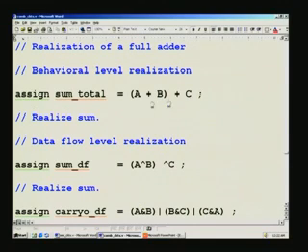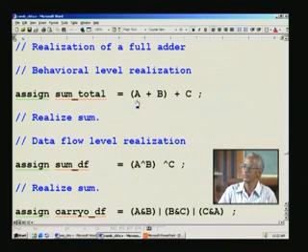We have seen 3 types of full adders. One is a behavioral level. This is the best because you need to write just a plain addition symbol as such. All of them are 1 bit, and you add A and B. There is a bracket I have explained earlier also, to guide the synthesis tool, because it cannot make a decision all by itself on what you intend doing. So, you have to tell the synthesis tool to do this in parallel with this.